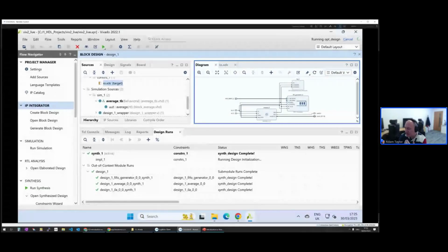I understand now. Yeah, so you can turn on and off if you want to drive external FETs. Everything that's happening in the FPGA is happening truly in parallel. So if you wanted to turn all of the I/O on and off at the same time, then you could. You might run into an issue called simultaneous switching outputs or ground bounce, but I doubt it in what you're trying to do. So you could literally have a port of 8, 9, 10, 16, 24 switching that way.